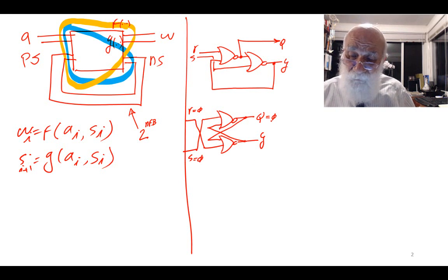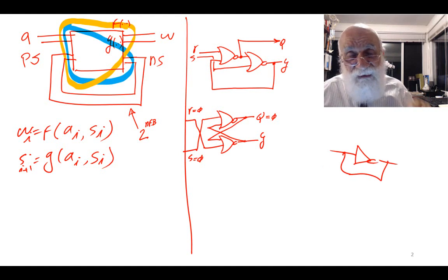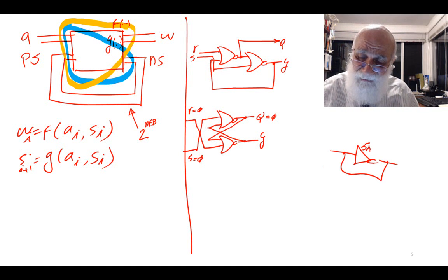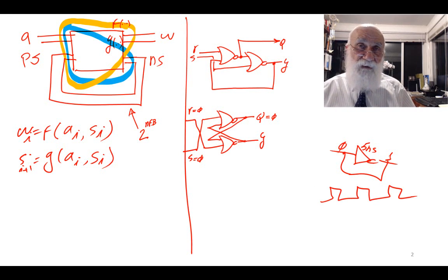By the way, let me say something. This is also a circuit with feedback, and of course this has memory. You know why it has memory? Because if this is 5 nanoseconds delay, you put a 0 here, this is 1. Now it remembers that 5 nanoseconds ago it was 1, so it toggles, now it becomes 0, and therefore this is a circuit that oscillates. You put more inverters, the frequency of oscillation becomes smaller, the period gets larger.